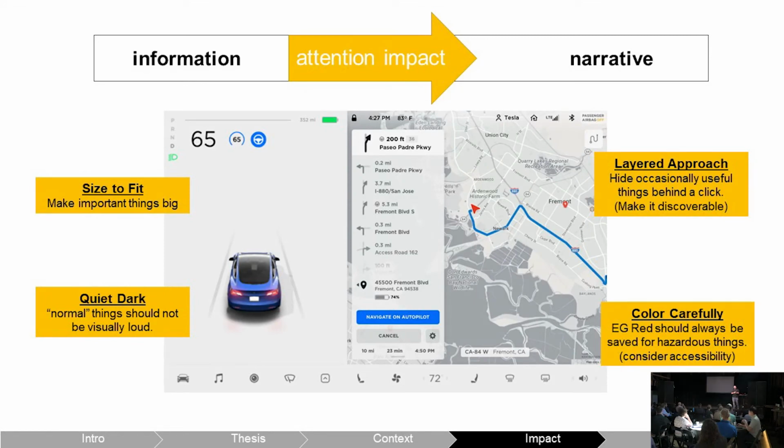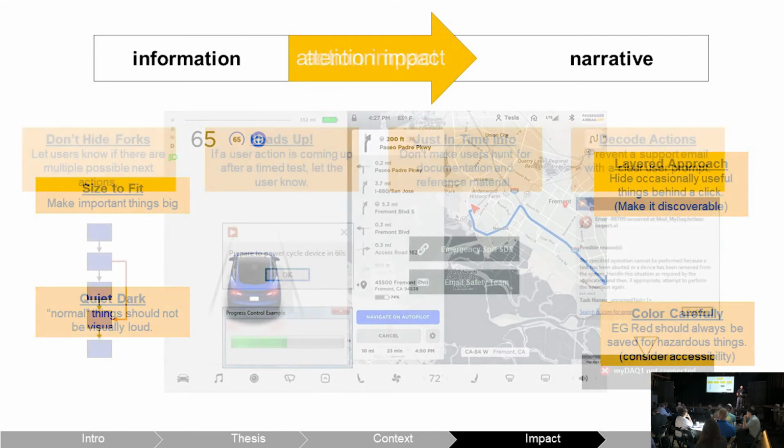And then you do have to think about accessibility. Don't encode a lot of information into color and then forget that you have a colorblind operator. There are a lot of great tools where you can upload a screenshot, and it'll show you different types of color blindness, along with what percent of people are affected by that. But yeah, if you have a big red-green that tells you, yes, this went perfectly well, or run and leave the room, make sure that color is not your only way to know that.